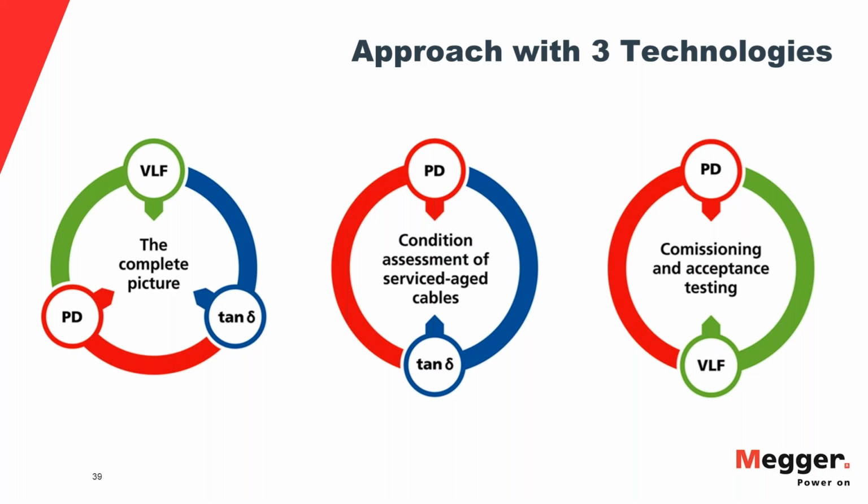When you find a bad cable, what type of locating would you use if you didn't plan on replacing the entire section of cable? Well, that is a very straightforward answer. You would just apply the standard fault location technology. So you would go for the arc reflection method, because it's most likely a pinhole fault on a solid dielectric cable.